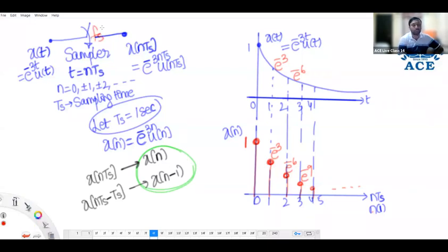Probably most of you are aware, to convert continuous to discrete, what is the sampling theorem requirement, sir? Sampling rate greater than or equal to 2 times the highest analog frequency. Blindly, whatever Ts we want, we cannot select it. Okay, so just go through the example. By using a sampler, we are converting continuous to discrete.